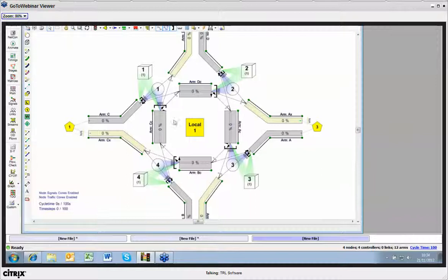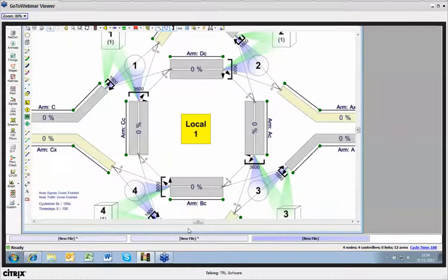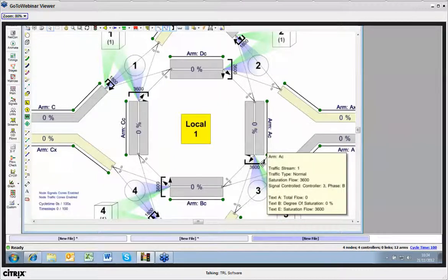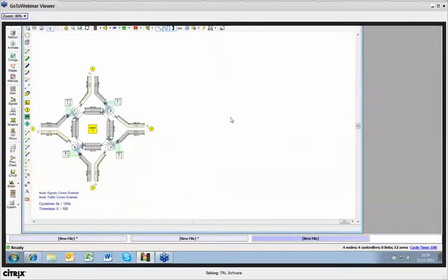So to set these particular traffic models, we can do that on either a network-wide basis, or, which is more likely what we're going to want to do, on a traffic stream by traffic stream basis. For instance, if I had 2 roundabouts here and I had a second one over this side, I would want to get the platoon dispersion effect between the 2 roundabouts correct.